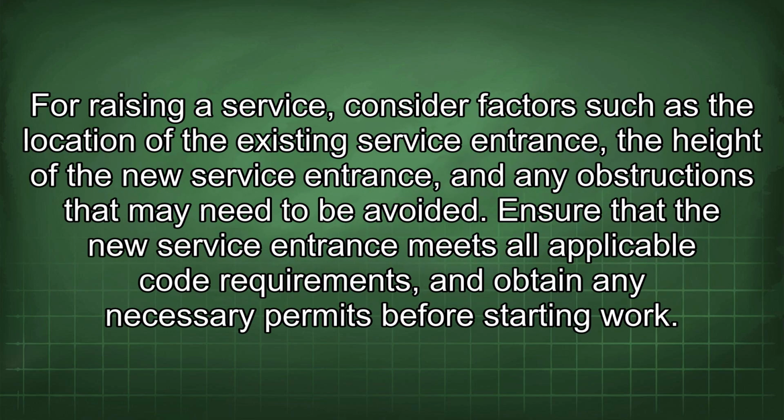For raising a service, consider factors such as the location of the existing service entrance, the height of the new service entrance, and any obstructions that may need to be avoided. Ensure that the new service entrance meets all applicable code requirements, and obtain any necessary permits before starting work.